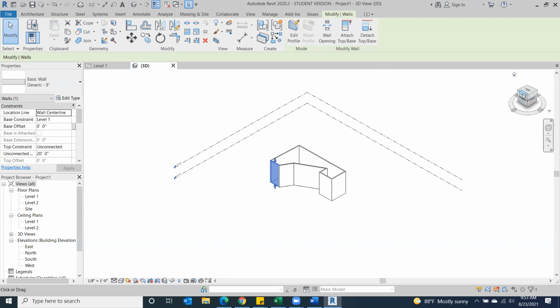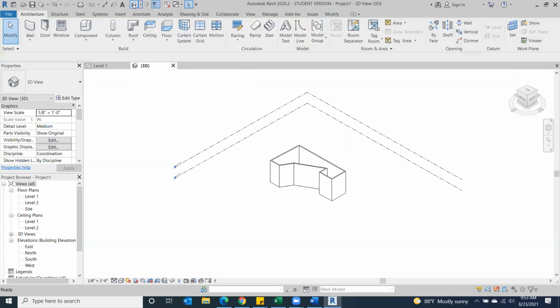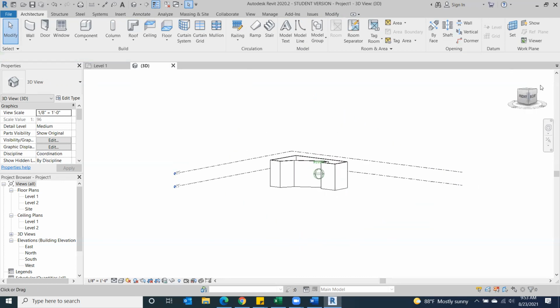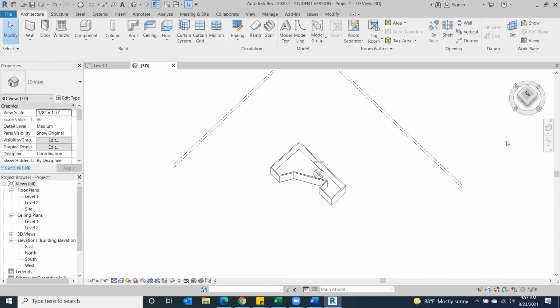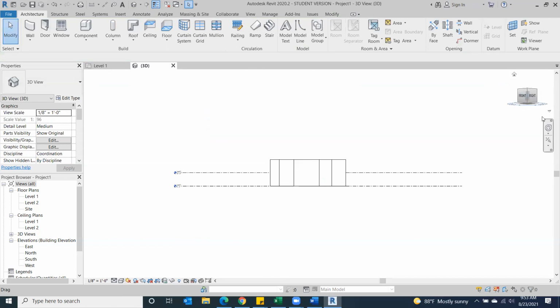Your cube right here. Yeah. Are you in 3D view? Did you go to the quick access toolbar and hit default 3D view? Okay, probably not. Hold on. Where is it on the quick access toolbar? It's either on the top section or the special. Oh, default 3D. Got it. Cool. And that should bring you back to this view right here. Yep. And now we can move the cube. You can click and hold it. Okay, cool. Got it. Great, excellent.